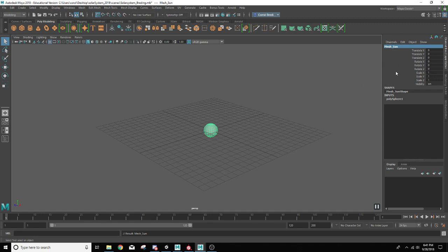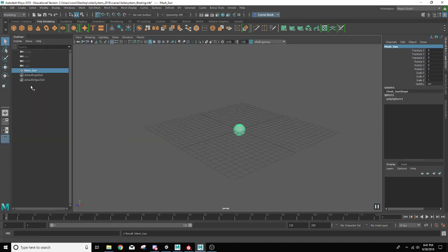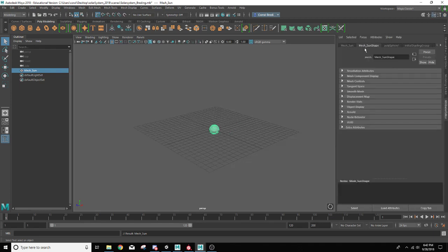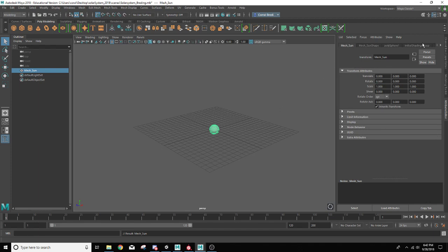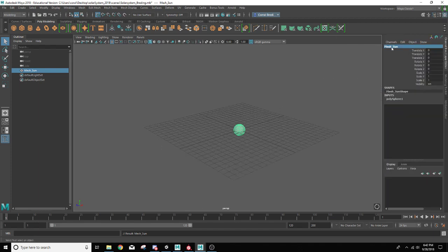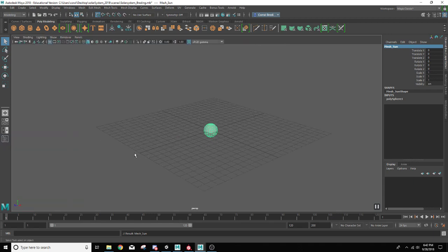One thing I do want to caution you guys against, I don't want to see any naming down here. The shape node is an attribute that's plugged into the object that you see in the 3D viewport. This does not translate over to the actual outliner, which is over here. This shows you the organization of all the objects and items inside your scene. If you name it over here underneath the shapes, this plugs into this object inside the attribute editor. This is essentially this right here, not the actual object itself. So make sure that you are naming right here, or if you want, you can actually name it inside the outliner as well. So again, the outliner is right here, this icon here. So let's go ahead and close that.